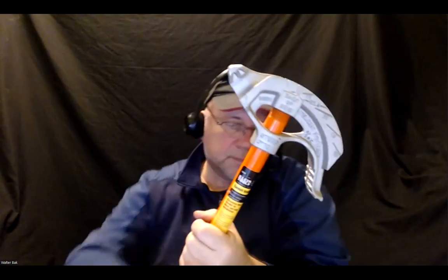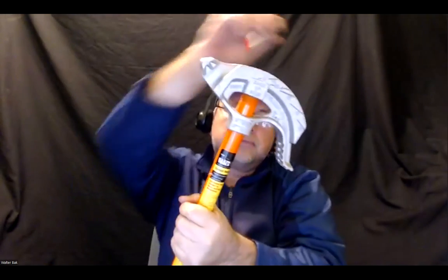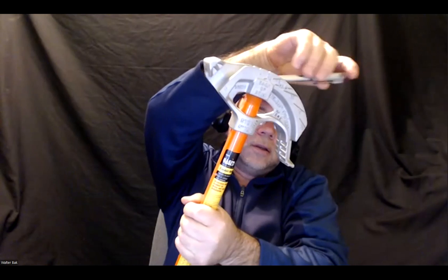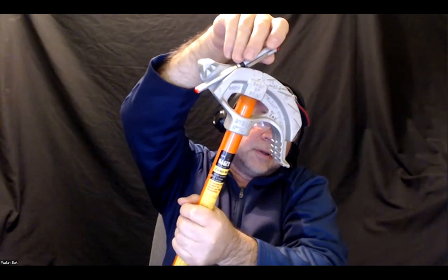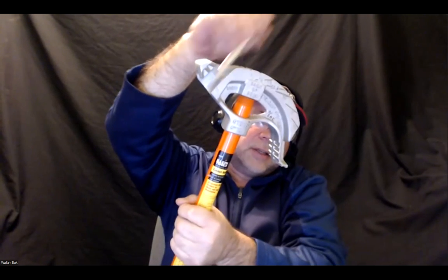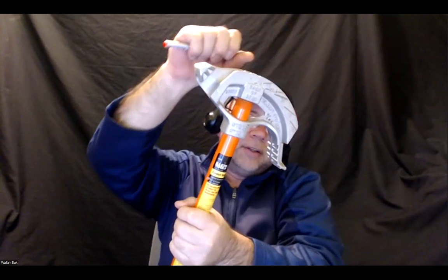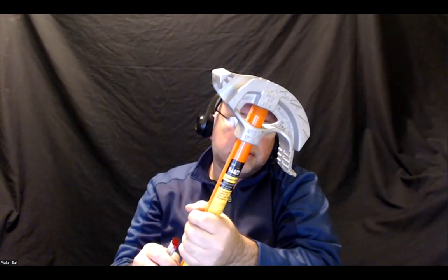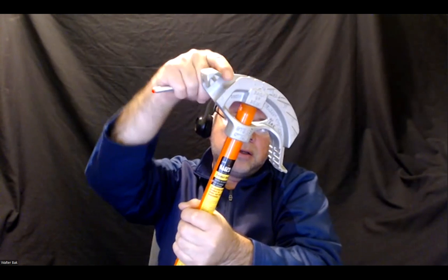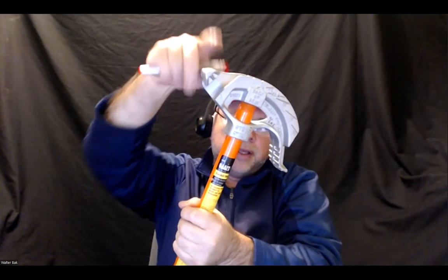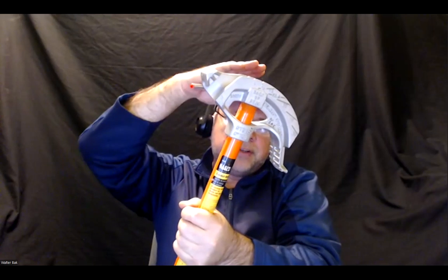If you make a mark on the pipe and align that with the arrow right here, and you do a 90-degree bend, that mark you made is going to be raised 5 inches from the surface. What does that mean?